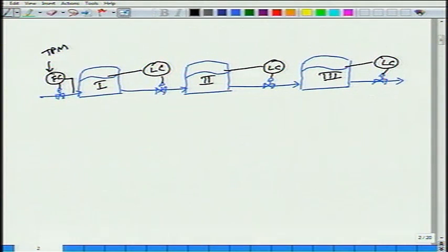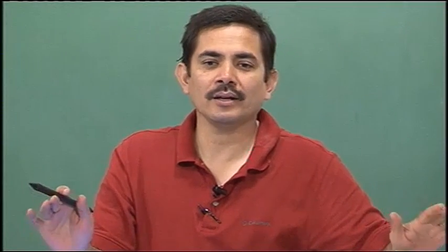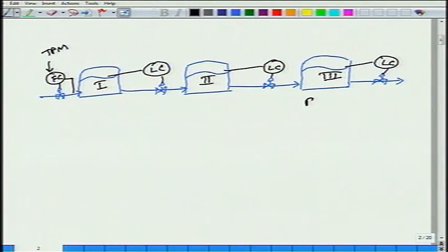Probably because in unit 3 some column became flooded, or some valve became fully open, or some condenser cooling water cannot be put anymore. There are n number of constraints that you can hit. Okay. So let us say unit 3 is my bottleneck. Star means, what does star mean? Star means bottleneck.